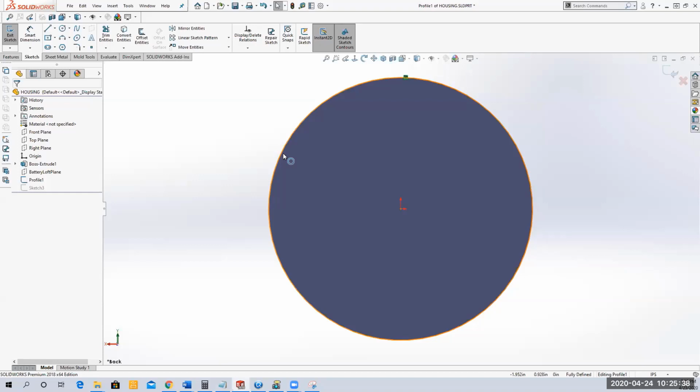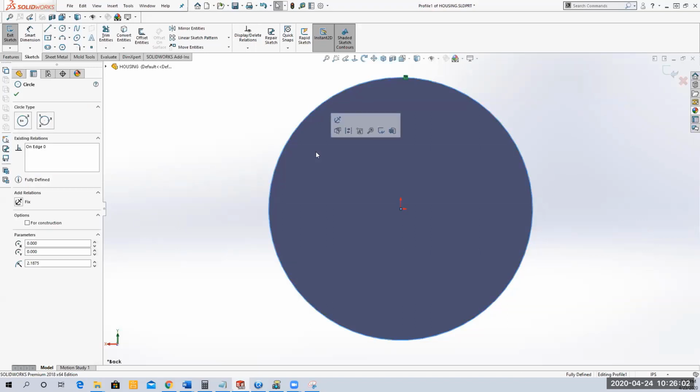And this is really important because a lot of people, and Elsa will agree with me on this, a lot of people miss this part where you're supposed to create a sketch on the back face of this extrude. And then when they create their loft, they just select the back face instead of selecting the sketch because they forgot to create the sketch or they missed that part. And then they'll get an error later on when we try to create a shell. Remember that, Elsa? Oh, yeah.